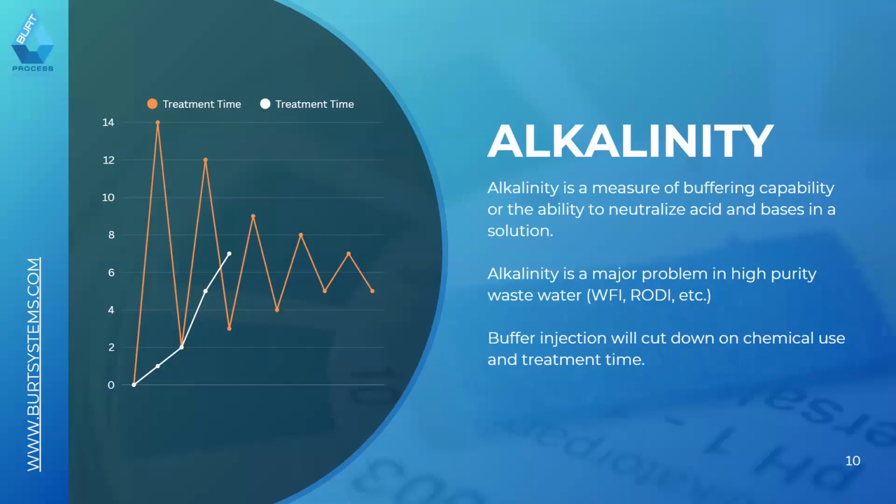I mentioned briefly before about carbon dioxide gas. Carbon dioxide gas is fairly viable if you have it on site. It allows the formation of carbonic acid when it's diffused into the system, which is a strong acid. It's relatively safe. It does change the overall design of the system a little bit. Now you're using essentially fine bubble diffusers that get sufficient surface area to allow for the CO2 to dissolve properly. There are other things that influence carbonic acid formation from CO2, like the height of the tank, temperature, things like that of the waste stream. But it is a viable alternative.